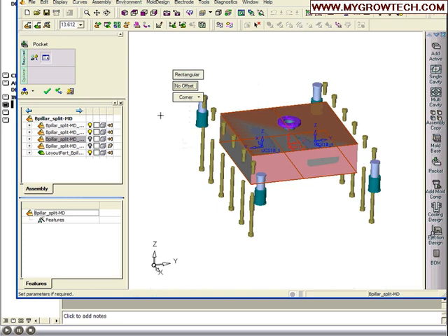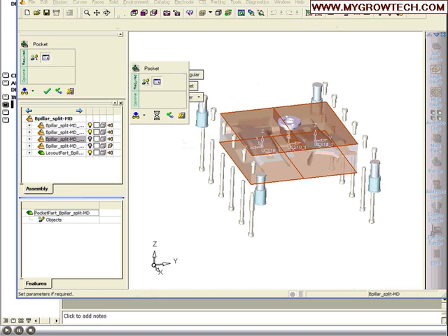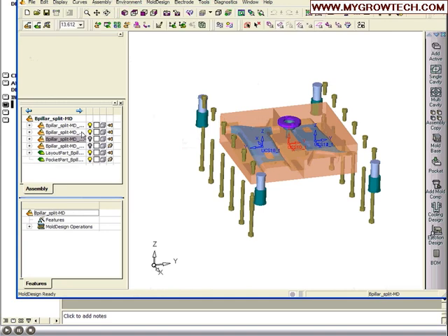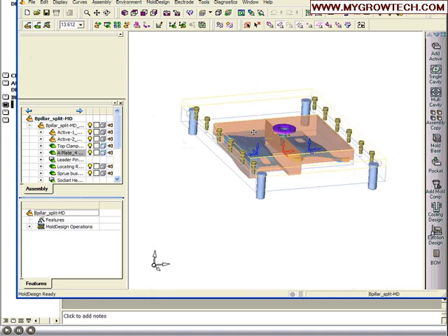Do you want a slip fit or press fit? Also, the corner condition. Is this going to be a wire EDM pocket with a sharp corner? Is it going to be a mill pocket with a radius in the corner? You can assign all those values. Let it calculate. Basically, it's just going into both the A side and B side retainer plates.